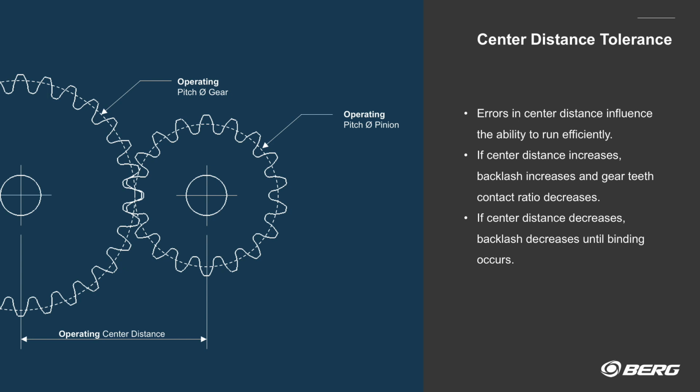As we discussed previously, in precise applications, backlash can be a critical parameter in the performance of the gear system. Backlash occurs due to teeth not making perfect contact and being able to move freely in the system. As the operating center distance increases, noting that operating center distance may not be the same as the designed center distance, the teeth have more clearance and hence backlash increases.